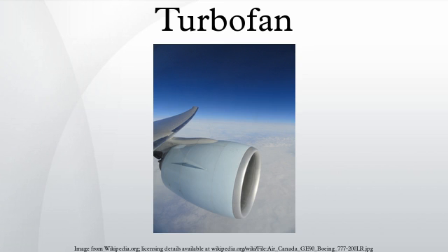Low-pressure turbine. Modern civil turbofans have multi-stage LP turbines. The number of stages required depends on the engine cycle bypass ratio and how much supercharging is on the LP shaft, behind the fan. A geared fan may reduce the number of required LPT stages in some applications. Because of the much lower bypass ratios employed, military turbofans only require 1 or 2 LP turbine stages.